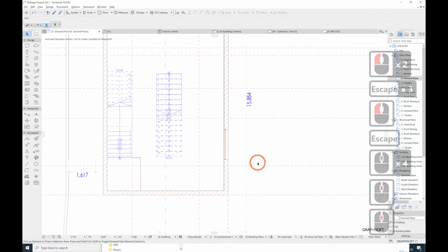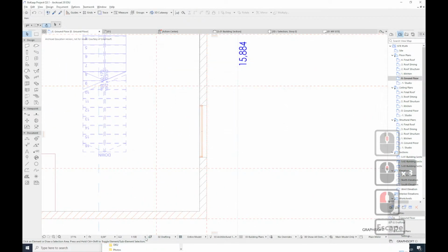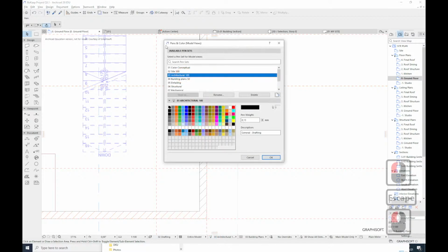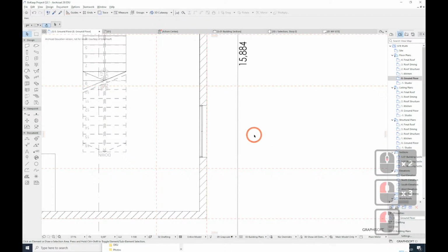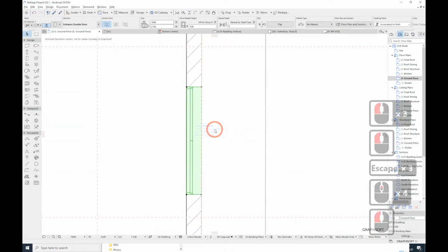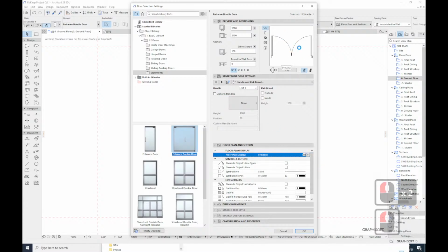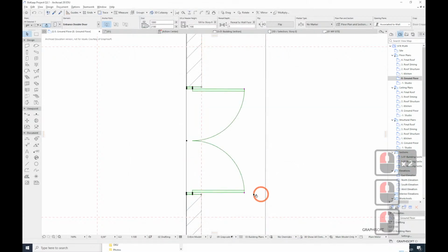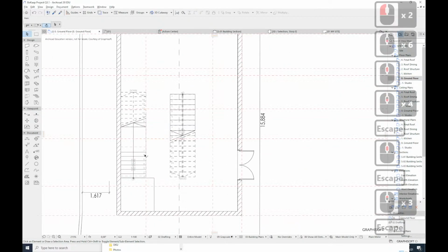Okay. Because this is designed, now you set your pen sets for drafting. So you've got my grayscales, here we go. Press OK. There we go. Now you want to show this as symbolic. So in here you're going to change it, this is where you should be working. Okay, so we've sorted this out. So this should be symbolic. Of course your symbolic line work is this symbolic over here. Much better. Wow. Now we're cooking with gas. Now the stairs are getting better too.